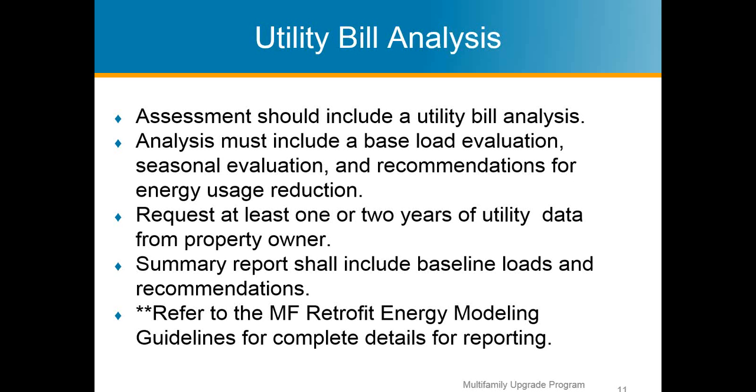So you want to request a minimum of 1 year of utility data. 2 more years, or the more data you have, the more accurate you can get. But 1 year, so you can see all 4 seasons of energy use, is ideal, is needed as a minimum.